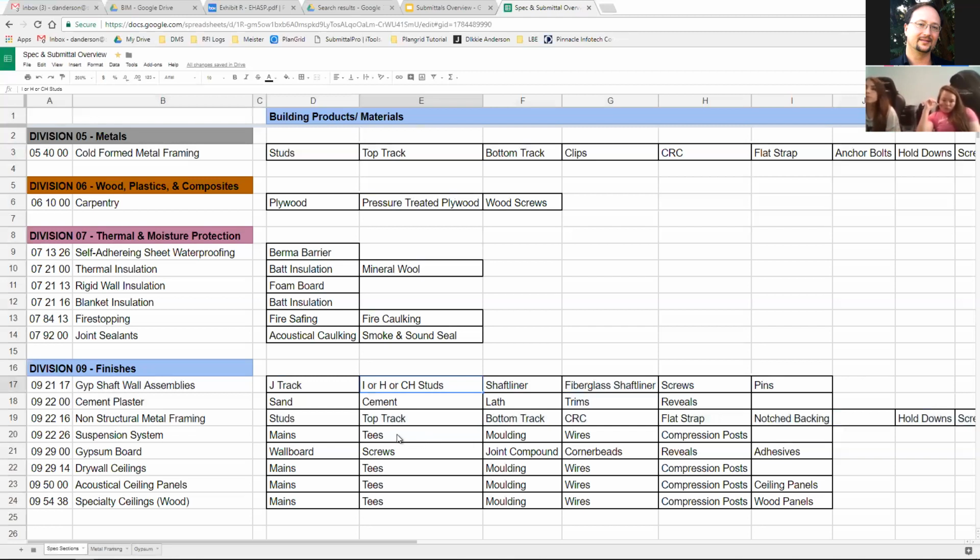Shaft walls are usually thicker building material, as it's designed to stop fire. Shaft walls go all the way through the building, and they usually have a minimum of a 2-hour fire rating. So the studs need to not melt after 2 hours. The drywall needs not to melt in 2 hours. So it's a different building using a lot of the same materials, but in a different way with different thicknesses. Okay?